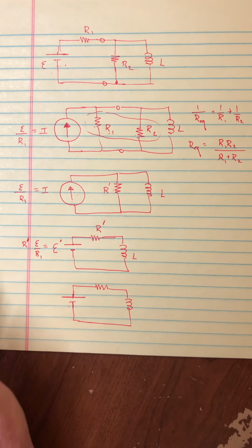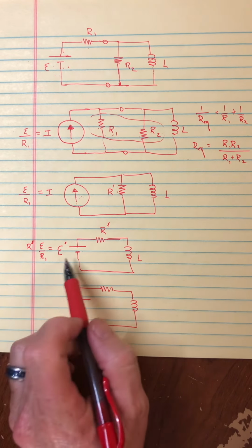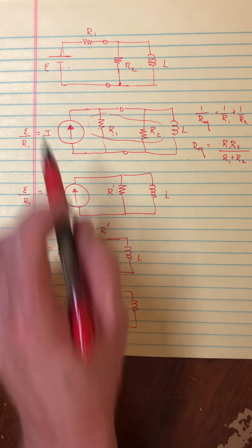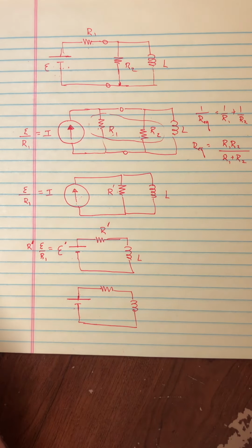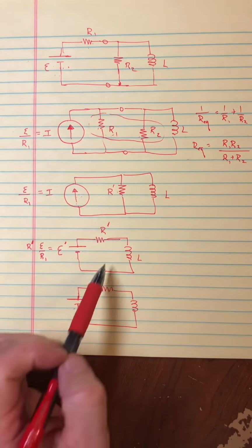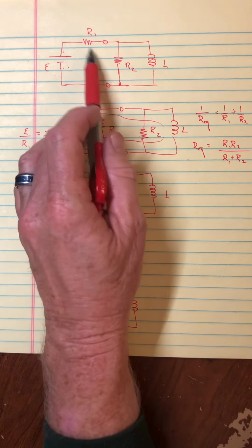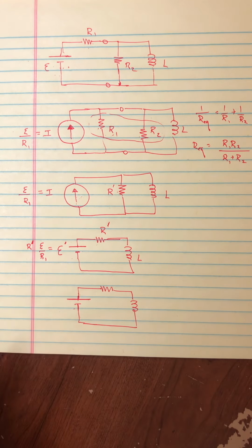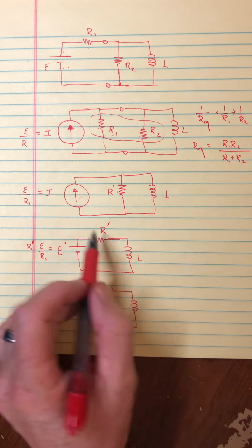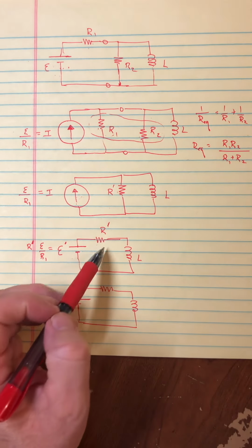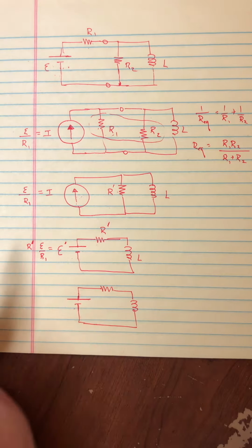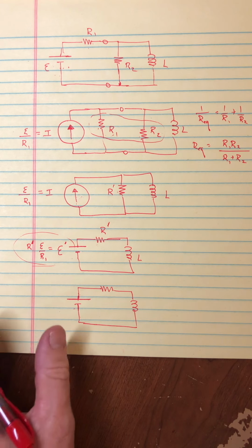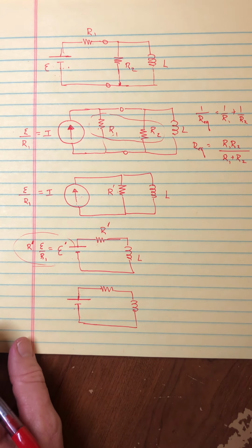And those two aren't the same. In other words, we don't go back to a constant voltage of what it was before. Which clearly we shouldn't. If we went back to the same voltage, it would be saying that these were equivalent to being parallel, and they're not. So there's got to be something different. It's not just that you can write these as being parallel with the same voltage. You have to write them as being in parallel with some different voltage, and that's this one. So that might be the hard part, and now that I think about it, maybe that would make this source transformation a little confusing here.